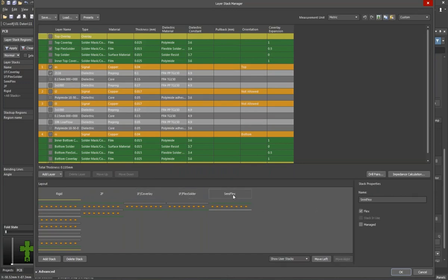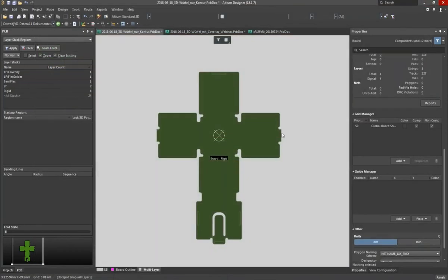And again, this is being shown here in Altium. So the depth milling is going from the back side, and we just activated the last prepreg and the top copper layer plus the top flexible solder mask. It is always important to have at least one full prepreg layer for the semi-flex bending area so that the glass inside this prepreg is not being damaged and the semi-flex can be bent well.